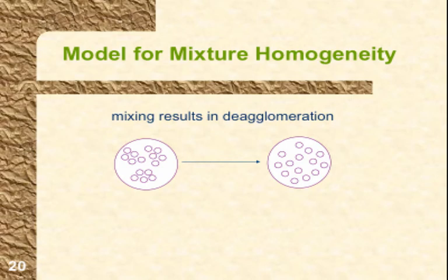I have a certain combination of materials, powder and polymer. Firstly, I need to know how much to mix. How much powder can I put in a mixture and still get uniform mixing? The second thing is, how much shear rate do I need to provide to make sure that agglomerates are broken down? Sometimes the shear rate is not enough. You can uniformly distribute the agglomerates without breaking them, and that's a problem. We don't want that, right?